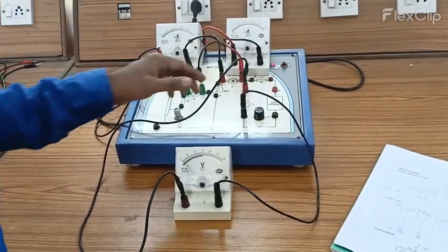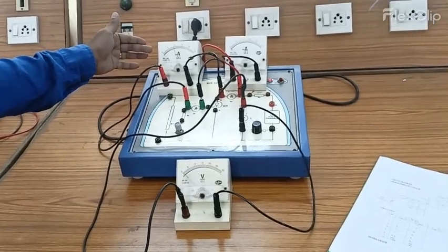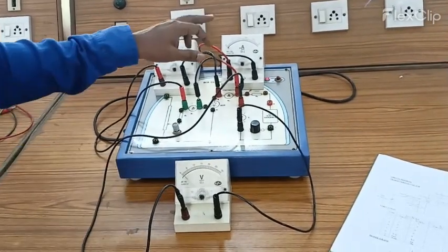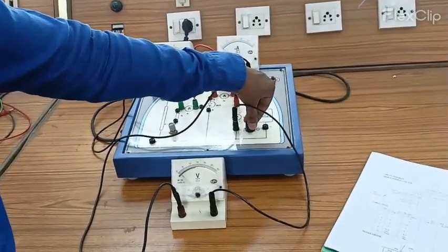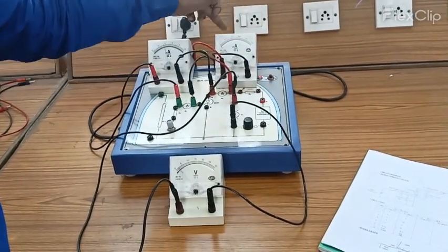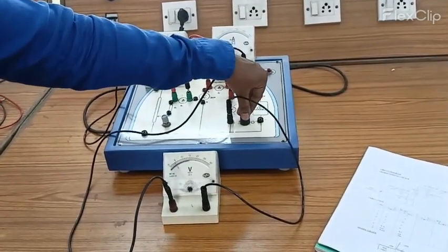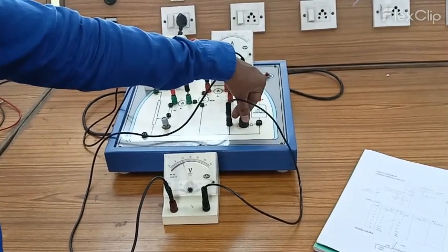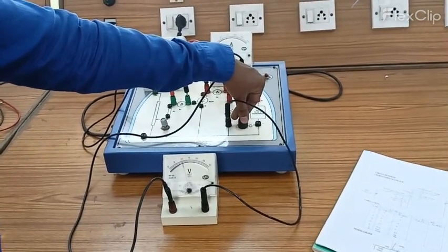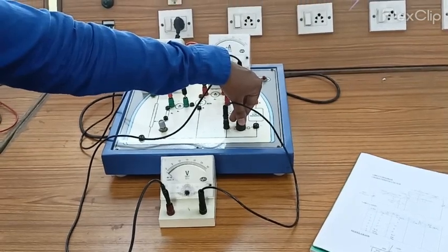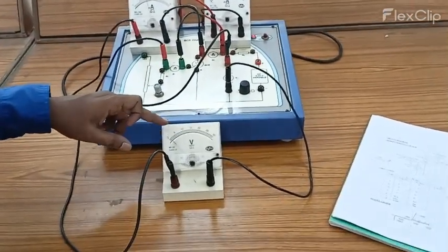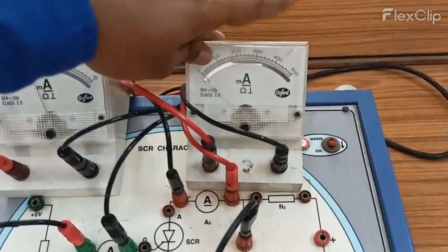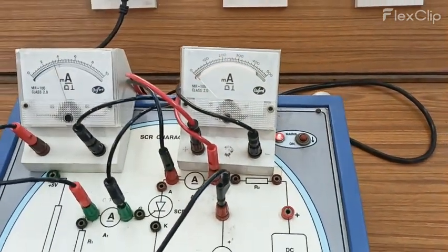You should mark the voltage and current for this gate current of 3.8 milliampere. For 0 voltage the current is 0, and when I increase the voltage to 1 volt or 2 volt, again the current is 0, and if we increase it to 4 volt, again the current is 0. At 5 volt the current is 0, and 6, 7, 8, 9, the current is 0. Now the needle is near 10 volt, and I am further increasing, so it breaks down, so the device voltage comes to 1 volt. Here this meter should read, but it is not reading, so there may be an issue with this meter, so we should change it.